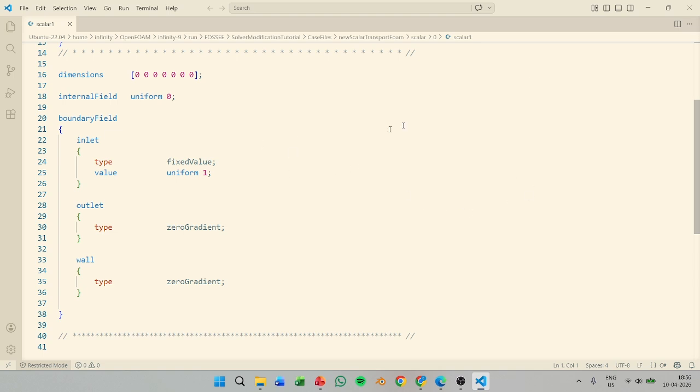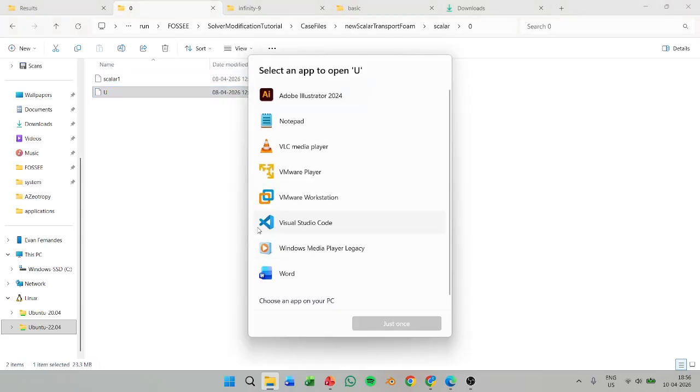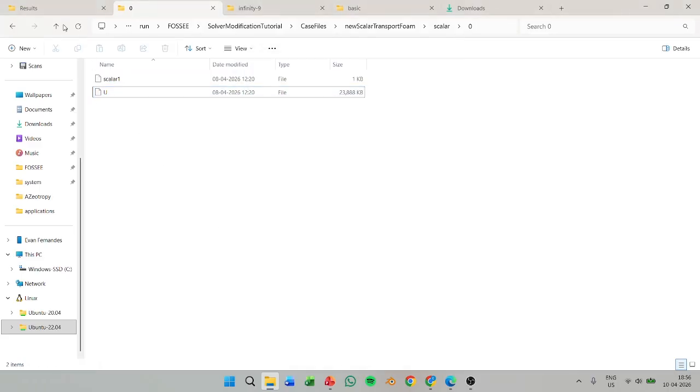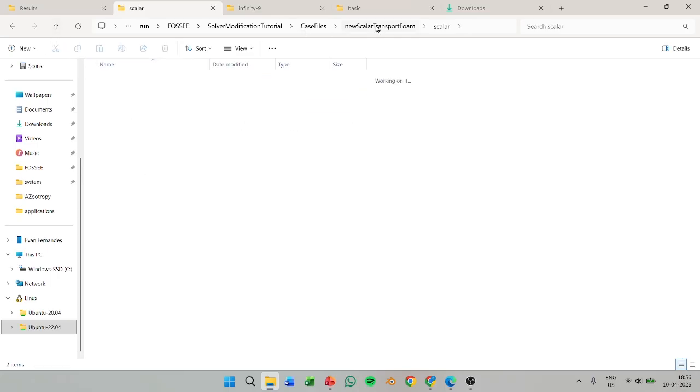However the flow is developing, it will just travel with it. You'll see how it happens. Velocity is the file that will be copied from your flow field. So if you were to see it this way, you would only have scalar1, you won't have velocity in the beginning. So let's first run that and then I'll explain everything in depth.